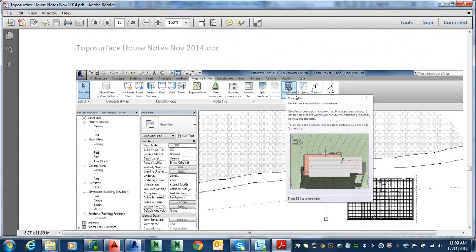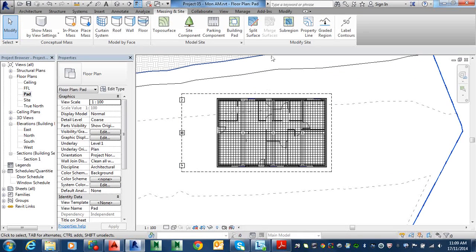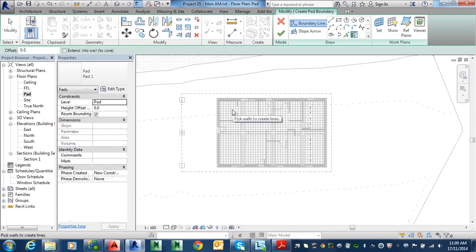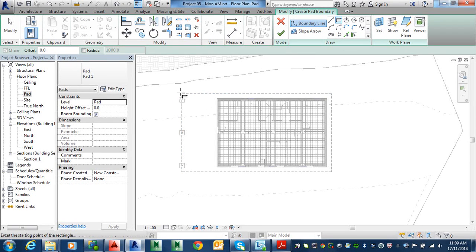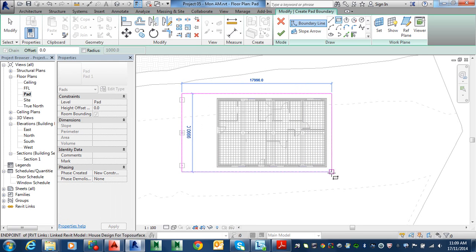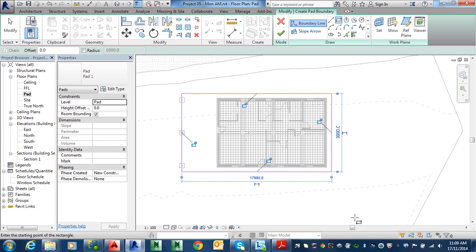It's showing there, which is very similar looking, but in my haste to get this out, it's supposed to be this command here, all right? That works better. All right, so let's invoke this building pad. And what we're going to do is draw a rectangle to sketch the building pad around just the outline of the roof of the house for now. I'm just going to click that tool over here, because once I click that pad command, these tools come over here. I can draw line by line, but it's easier for me to just draw a rectangle. So there's basically the sort of CAD style commands you can use, with just 2D. So that goes there.